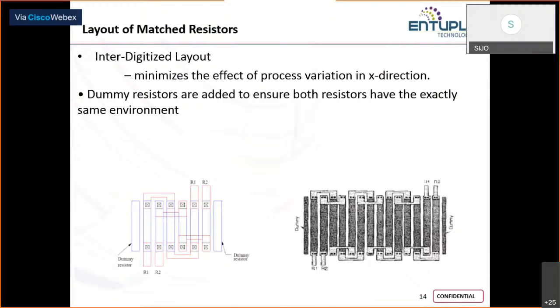So we also use dummy resistors at the end. You can see the dummy resistors which I have shown in the figure on the right side; at the end I have attached dummy resistors. Dummy resistors basically don't contribute to the system performance, but from the matching perspective, in order to provide an identical environment for all the matched devices of interest, we make use of dummies. The same thing we have seen for the MOSFET in the beginning.